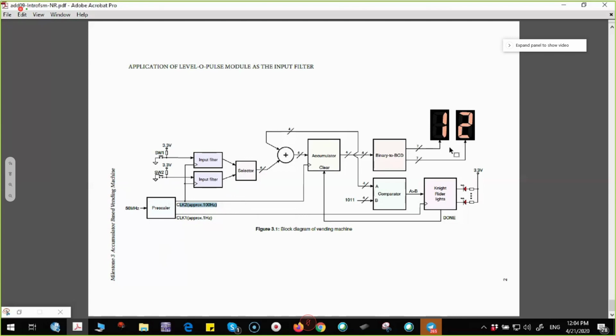BCD. This is like a 5-bit output, but you group this one into BCD. If you can group both into BCD is better, but I think it's not possible to group this one, so that you can see in binary, or when you do quarters, this one will appear as either 0 or 1, and this one in decimal. So this is just display. Actually for this one you would need the 7447, the BCD to 7 segment. So you skip that part.